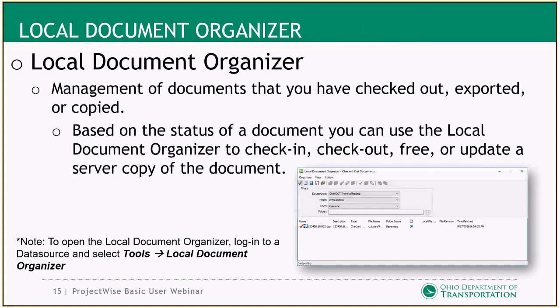That was one way of managing the documents. There is another way inside ProjectWise to manage your documents. If you go under Tools and Local Document Organizer, you can manage your documents that you have checked in or checked out. As you can see here, we have one checked out. You can check this document in, you can free it, you can update server copy from this window as well. So that's just an easier way to manage all the documents that you have checked out or copied out to yourself.